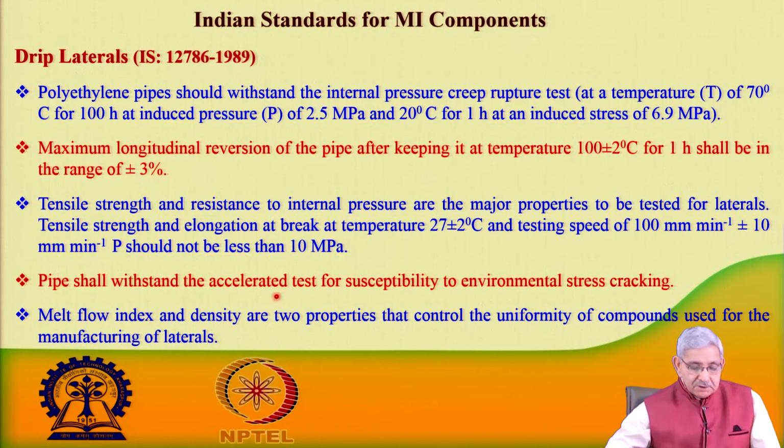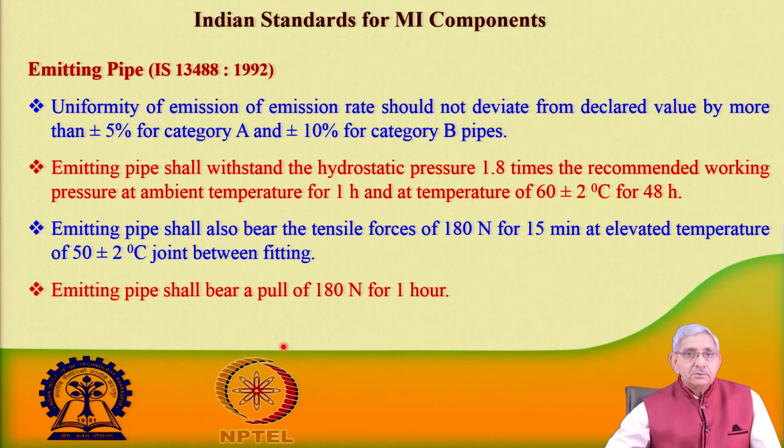Then pipe shall withstand the accelerated test for susceptibility to environment stress cracking. And so, in a short period when we are giving such tests, this will be useful for a longer duration study. One can know beforehand in the laboratory conditions, when tensile strength or melt flow index are tested, so that it is properly understood that it is working.